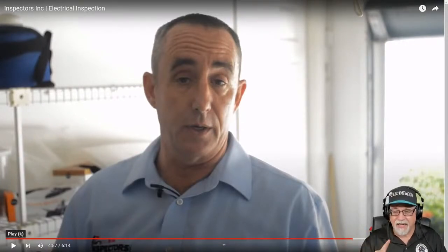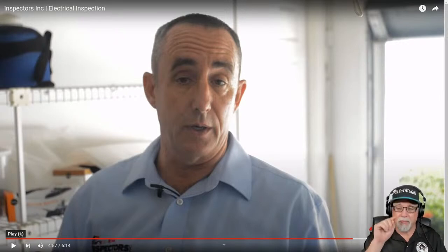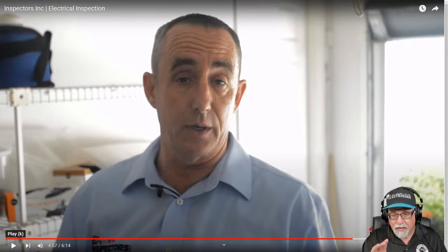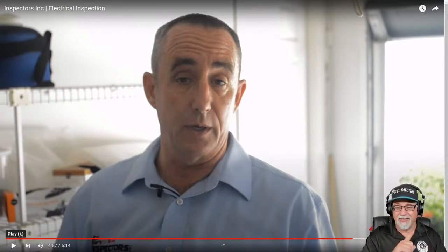Now, this is a test device. You should be testing your GFCIs in the field or your home by just testing the test button on the device that's mounted in the receptacle outlet box. You should be hitting the test button. Now, these devices are great for home inspectors and things like that, but you got to be careful because these things can be fooled, okay?